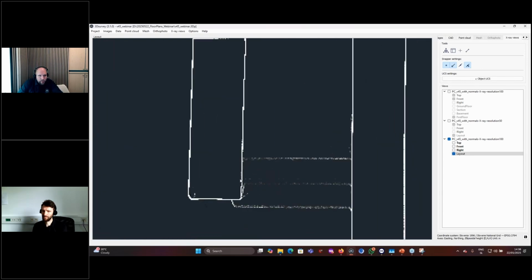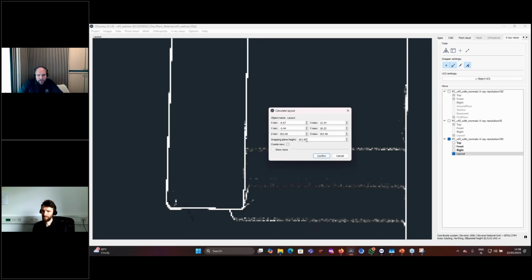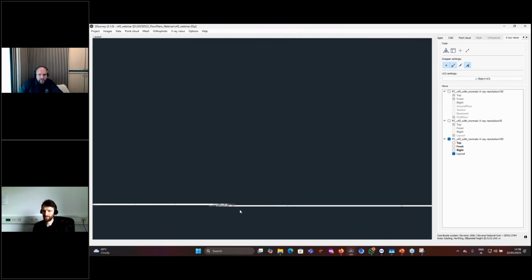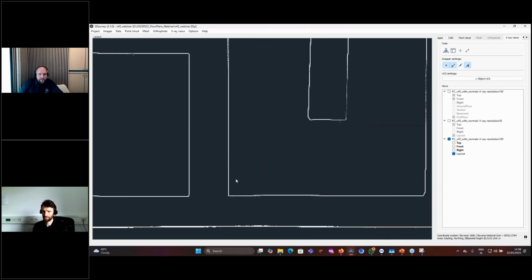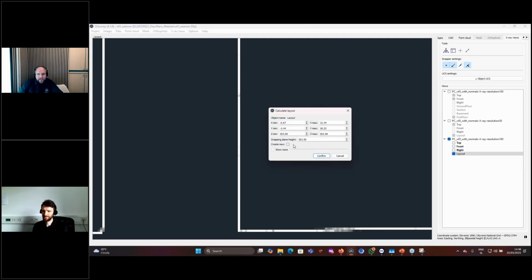And if we are not happy with the parameters, we can go in here and press recalculate. Maybe in this example, I can increase color transparency. Let's try to increase it to 95%. So now these walls will be less strong white color. Press confirm. And what if you wanted thicker walls? If you want them to show up thicker, you would go in here, again recalculate, and change this to 2 centimeters.